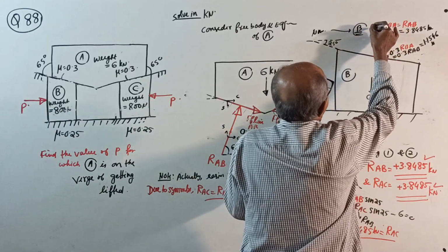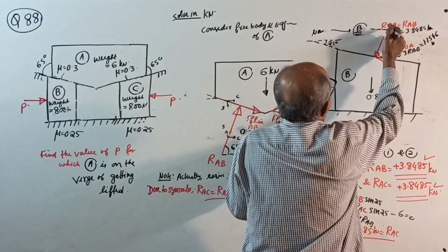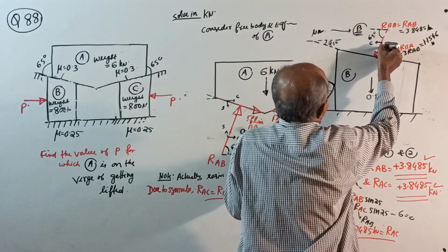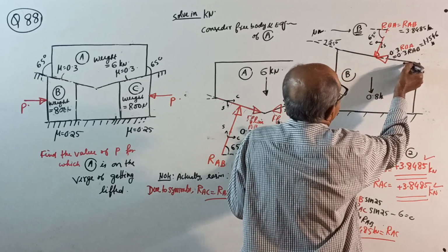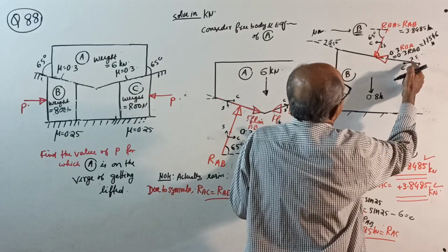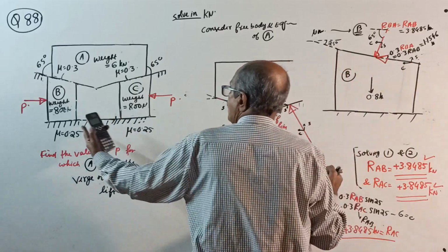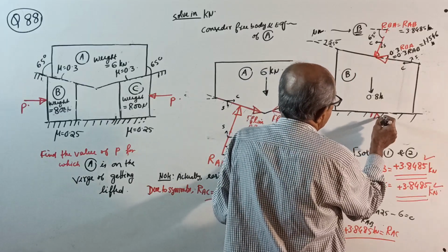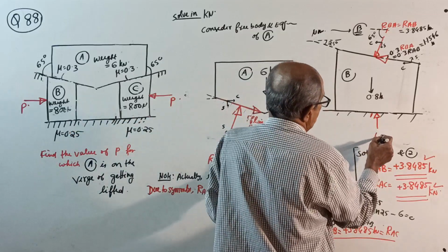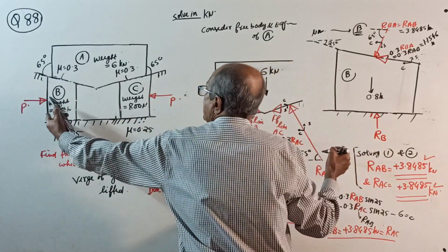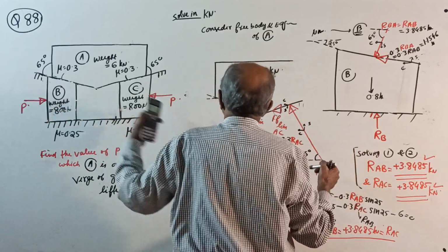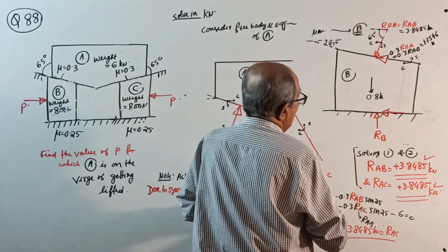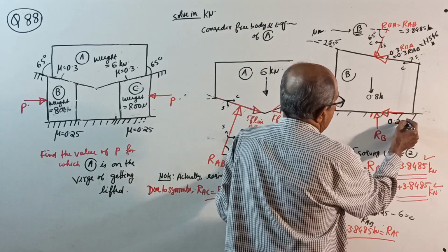See, this angle, how much? With horizontal, this will make 65 degrees. So later, cos and sine with respect to 25 degrees, here. This contact surface, the normal reaction, is moving which side? This side. A normal reaction of RB, no suffix required, and this is moving right side. Since I am doing this block, friction is left side, that is, the coefficient is 0.25 times RB.